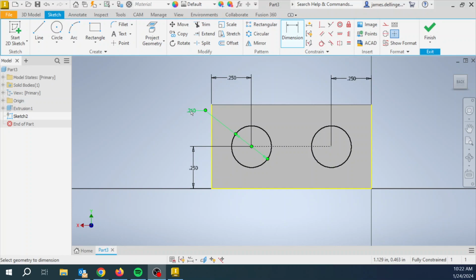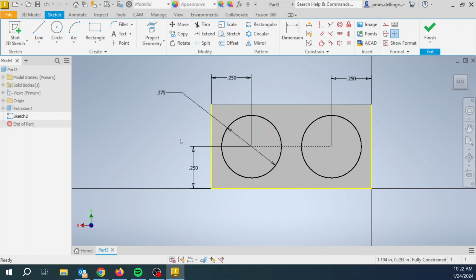So that's why if I go here and I change it, and by the way, if you want to change this, just double click it, and then you can say 0.375, and then both of them are going to change. By the way, I'm deliberately trying to make it more like a Lego brick now. So you can go back and change that. My design intent is I want these to be the same, so I added the equals constraint. And so now those are forever the same.